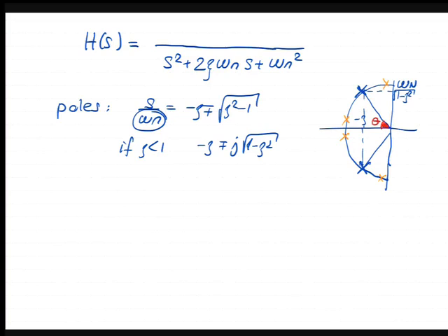Then what that means is that, cosine of theta, this is zeta, right? This is 1. If omega n is equal to 1, that's 1, right? So cosine theta is zeta, right? So that means you have two poles that make an angle of theta with the real axis, and their distance from the origin is omega n. That's why this parameterization is useful.